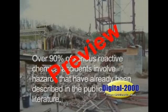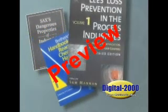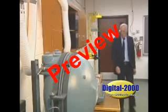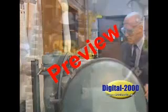The CSB's 2002 study found that over 90% of serious reactive chemical accidents involve hazards that have already been described in the publicly available literature. The board recommended that, to better understand reactive hazards in their processes, companies should consult multiple sources of information and conduct specialized testing if necessary. Collecting adequate safety information and data is especially important when scaling up a reactive process.